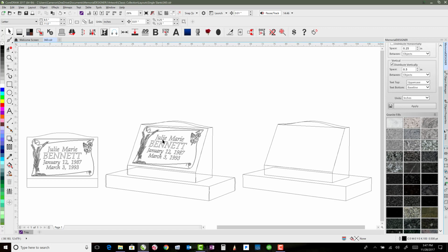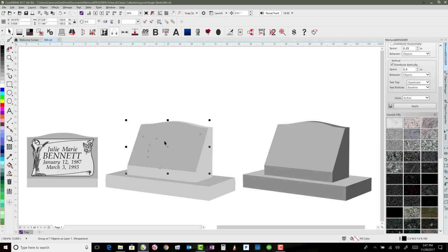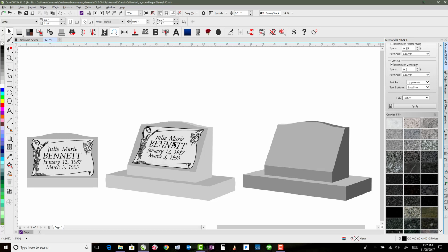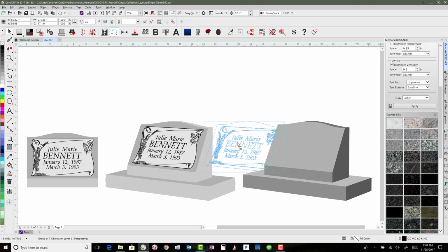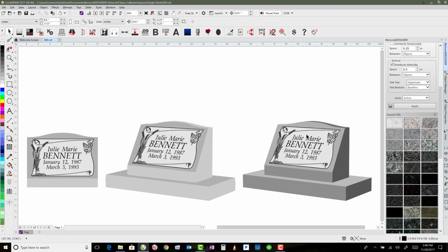I'm going to go to wireframe hitting view so that I can see that again. I forgot that I should hit shift page up to bring it to the front. Had I imported the slant before I made my copy, we wouldn't have had to do that. But anyway, we can now take the same thing, drag and just right click again to make a copy, and then hit E and C holding down shift while selecting that as well.